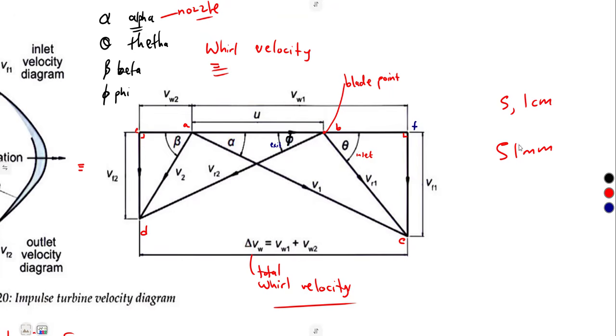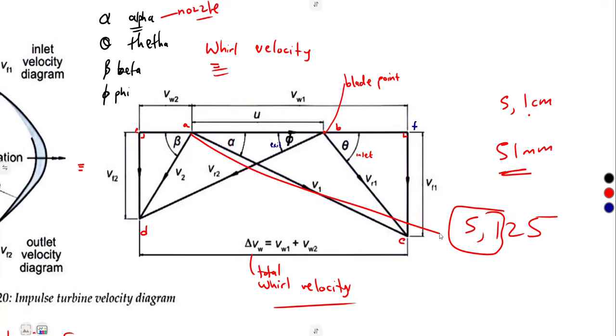So it is better that you work with one decimal place when you are working with measurements in centimeters or millimeters, whatever will be given. The other part, round off as usual. You can just use three decimal places. But for those that you're going to measure in construction, it will be difficult for you to construct 5,125. But if you have 5,1 centimeters, you know it's 51 millimeters. You can measure 51 millimeters directly with the ruler. So that is what I'm trying to say.